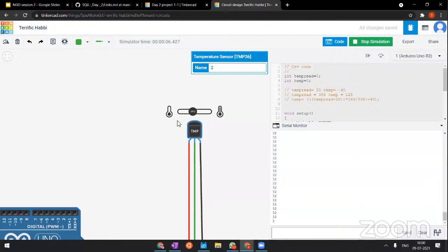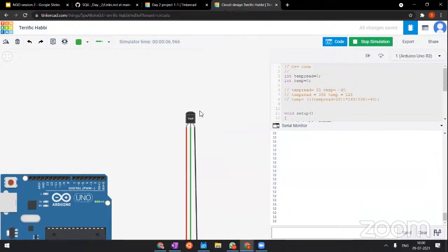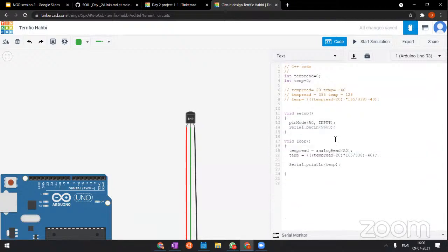So this equation works, but as you can see, it is not very easy to come up with. You need some time, like off computer. You need to look at the 2 points and come up with the equation. So for that, Arduino has given us a very easy function called map. This is an inbuilt function in Arduino. What it does is it is going to map. I'll type down the syntax and explain it to you.